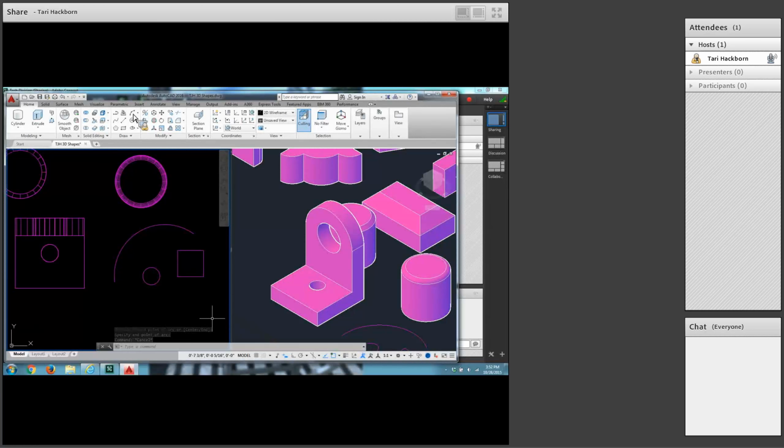Okay. Now, I want to let you know right away, we want to do a sweep with this, and the directions in the textbook won't work. They have you sweep one shape along the arc and then sweep another shape along the arc. You can't sweep them separately. After you sweep the first one, the path disappears. The arc will disappear. So a few releases ago, AutoCAD decided, once you sweep something along a path, it's going to just disappear. So you have to sweep the circle and rectangle at the same time. And you can do that. Just draw this little line right here. Okay. Move your circle. Get the center point of the circle. Shift and right click, put it on the midpoint of the line. Good. And then just erase the line you drew. All right.